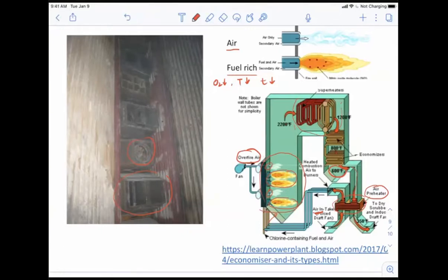So you can have a heat exchange and warm up this fresh air to a temperature of, let's say, close to 100 Celsius, right? So in this way, you can extract the heat and then introduce them into the combustor so that you can further increase the reaction rate and also the temperature of the flue gas. So this is another way to save the energy out of the combustion.